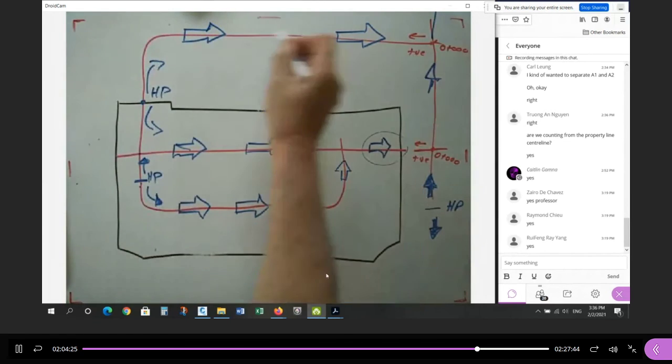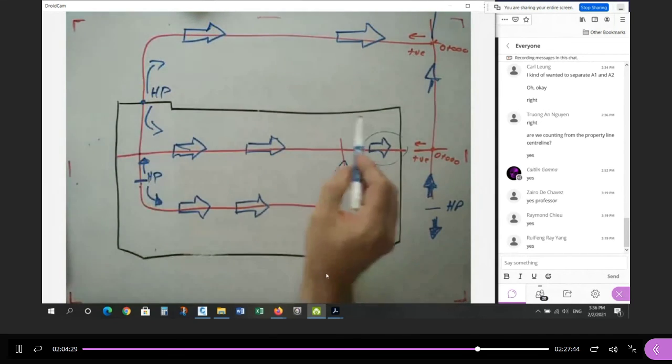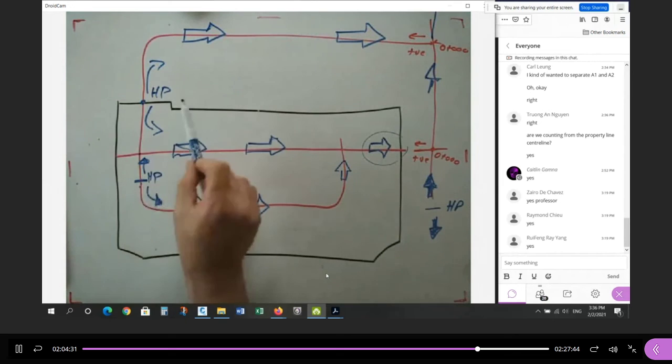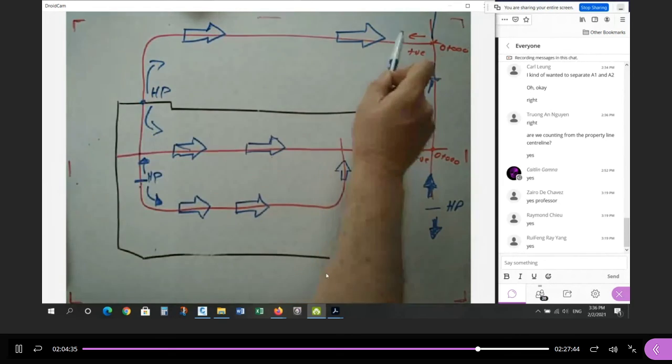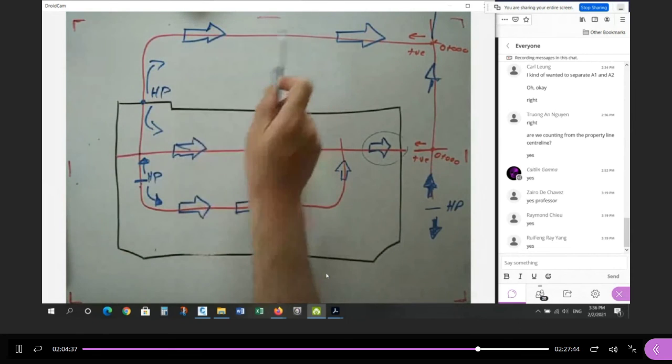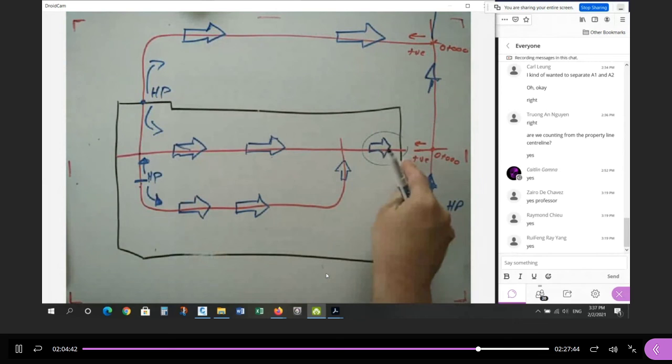Why? Because the existing sewers on Chugach might not be able to handle it. So the drainage area, which I'll show you later, assumes that the Chugach high point is here. This water goes this way and these sewers are sized appropriately. And then this entire area is supposed to go this way, out this side.